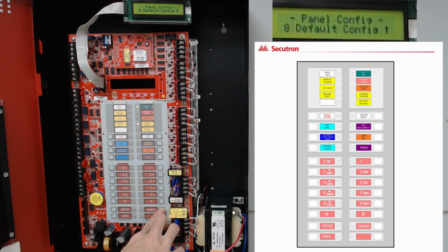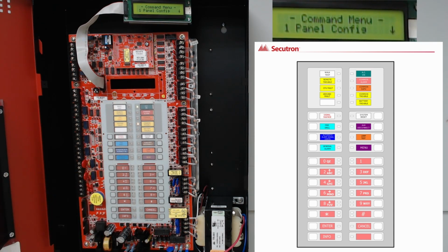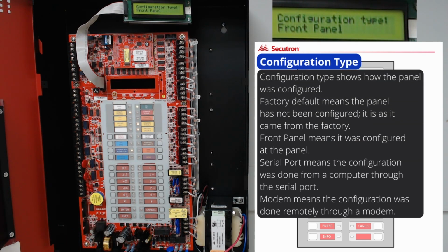By hitting cancel again, we'll back out through to the command menu. We'll need to silence the config access trouble, and then we can scroll down through our command menu options. Our next option under command menu is config information. By pressing enter, we'll be able to see our config information type.